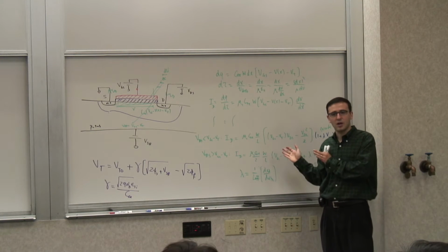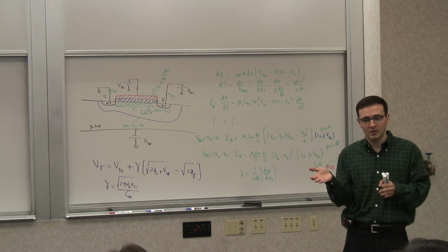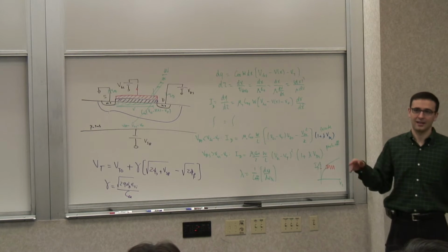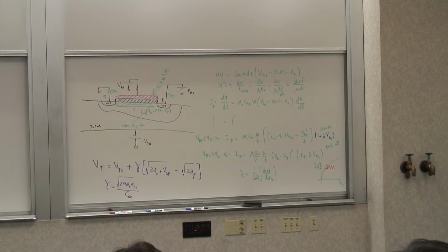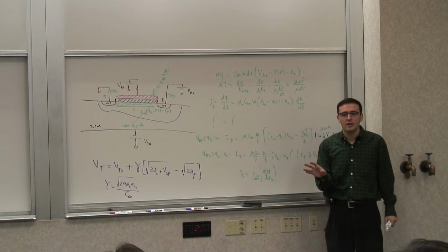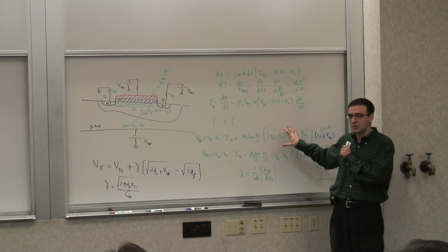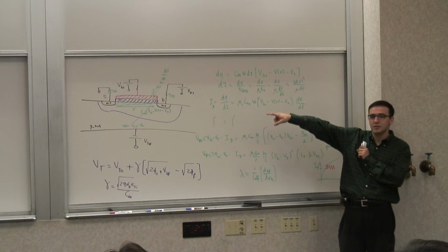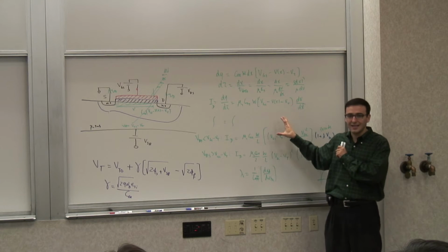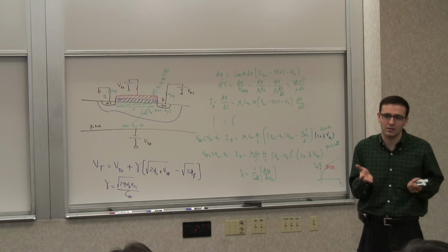The simulators, for instance, for MOSFET have a large number of different models that you can choose from. So if you use level 1, you pretty much are using these equations. Just the kind of the most basic, hence the level 1, right? And there's a modified version of that which is level 3, which captures some of the other effects that we'll talk about. But the equations they use are not differential equations. The expressions that we use for currents and all those things are not the original differential equations. They are more sophisticated models captured through the analysis physics, but most of the DC type of models are basically partially curve fitting models.